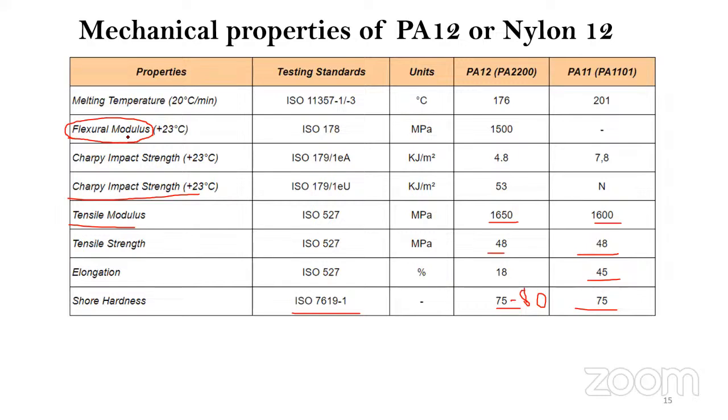See, after molding some specimens, as per tensile modulus ISO 527, the specimen will be of size 80 mm length, 10 mm width, and 4 mm thickness as per ISO. So in the UTM, Universal Testing Machine, we bend the material from the center, and it gives you the flexural strain and flexural modulus value. Means how much percentage we are bending. As per ISO, we will do around 3.5% bending. So in that bending, how much value is coming, that is the flexural modulus.